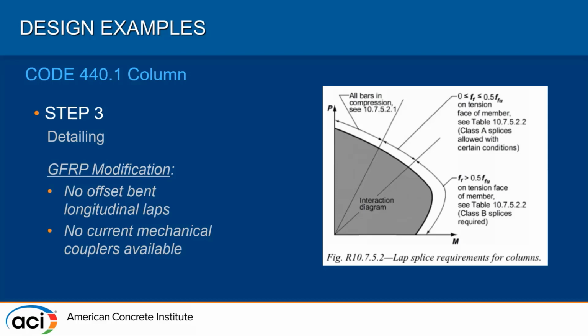And be aware that a lot of any shape cannot be field bent. So your contractors need to be aware that they can't order a whole bunch of number 3s and field bend them. They need to be very aware that there are some limitations, but there are pros and cons to that, I think. I think it's nice that all the shapes show up on the site and they can just start installing. They don't have to have a truck bed with a jig on the back of their truck bed bending these bars.